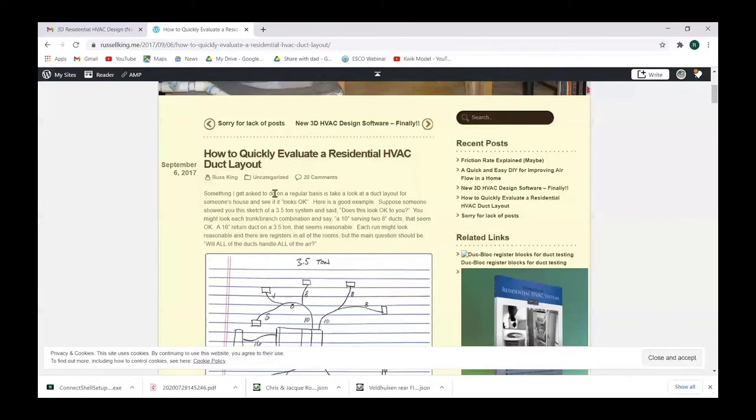Because the framing factor is basically you're looking at a wall and saying what percent of that total area of wall is wood. Okay, so 2x4 at 24 is 0.22. Interesting. Yeah, I'm not sure why that is. Not sure why it's changing in Rightsuite like that.